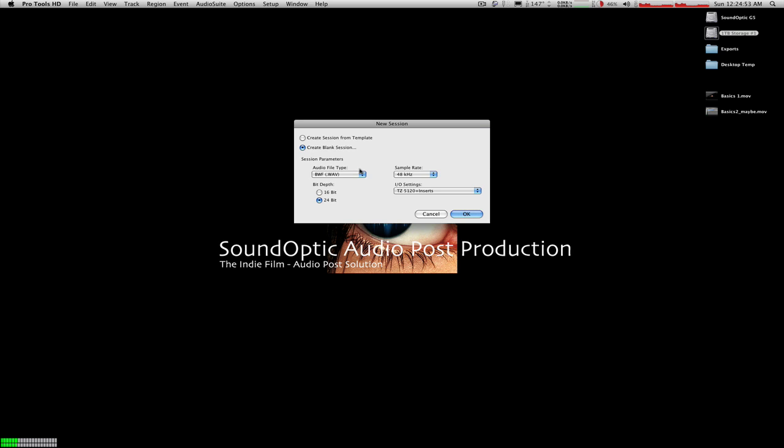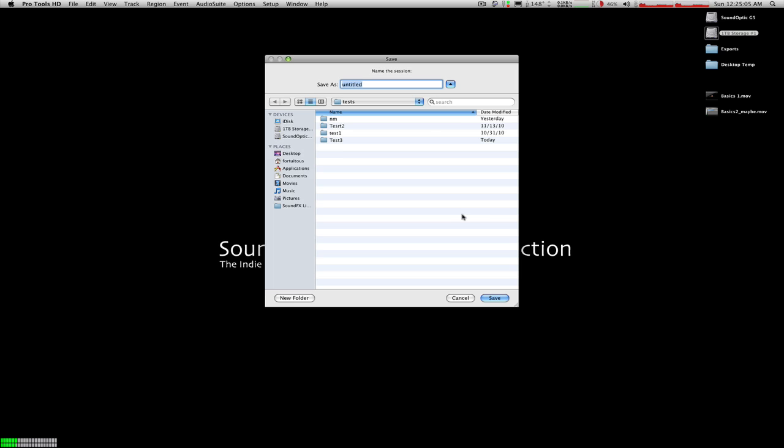We'll create from a new session, and I'll stay with the old standby here, 24-bit 48K broadcast wave, and I'll stick with my general 5.1 plus 2 routing. I'll call this session Avatar. And notice that defaulting to the last place, I have a folder on my storage drive called tests at this point with 3 or 4 very generic ones, but I'll call this one Avatar and hit save.